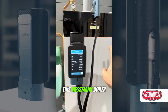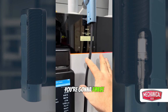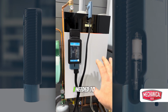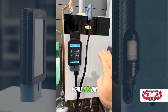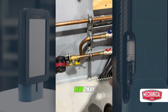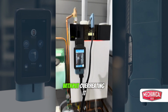The manual for this Viessmann boiler tells you to use the actuator test mode that's built into the control. You're going to force this boiler into low fire, okay? I need it to be at its lowest input rating so we could just get a baseline and see how things are burning and operating while it's on its lowest input. I do have to have that call for heat. Okay, so I've got that call for heat happening. I can dissipate any heat the boiler is producing without overheating it, okay?